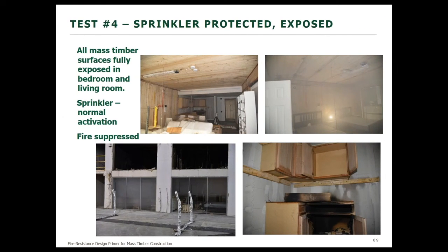Test number 4: what I've got before you is, again, all mass timber surfaces fully exposed in the bedroom and living room, with the sprinkler under normal activation. As you can see, the activation occurred right around 3 minutes, and it suppressed the fire. The fire was contained essentially to the cabinet where the fire source started.